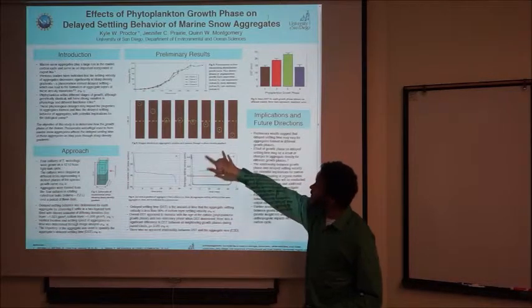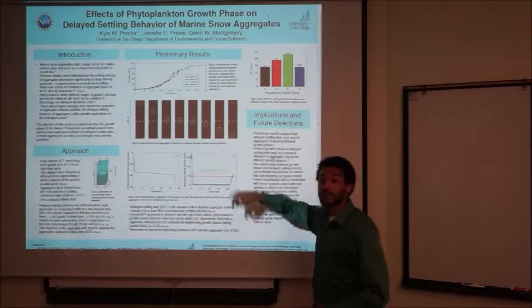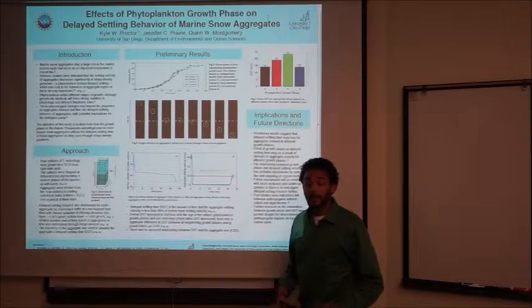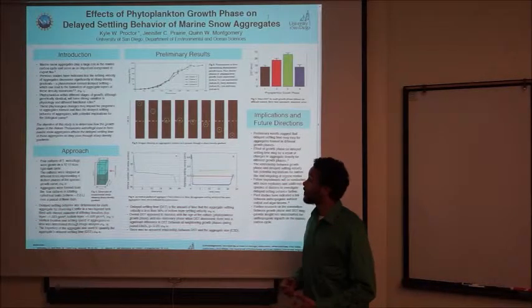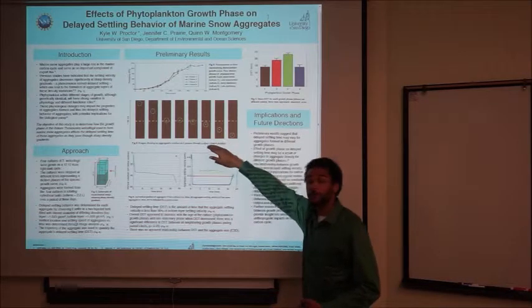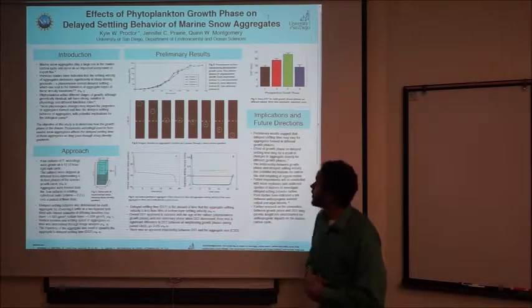It remains at that sharp density transition for roughly 15 minutes before it continues to settle again linearly in a few seconds. You may wonder, why would that happen? This is due to a phenomenon referred to as diffusion limited retention. Because of the extremely porous nature of these aggregates, it takes time for that lighter water to be diffused outward by the more dense water in the lower portion of the tank before the aggregate can continue settling.